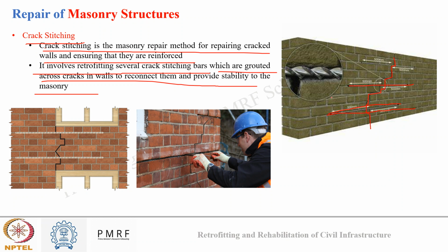So in this image you can see across the length of the crack, horizontal drilling was done, and in those drilled holes rebars were inserted, and these were later filled with the grouting material. So this will help me to arrest the cracking. So in these images also you can see how crack stitching activity has been carried out for masonry repair.